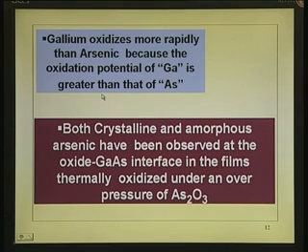That is real bad news. If you have arsenic at the interface, not because it is poisonous for you, it is because it is like putting a metallic layer between them. Elemental arsenic is suspended, it is like putting a metal layer there.